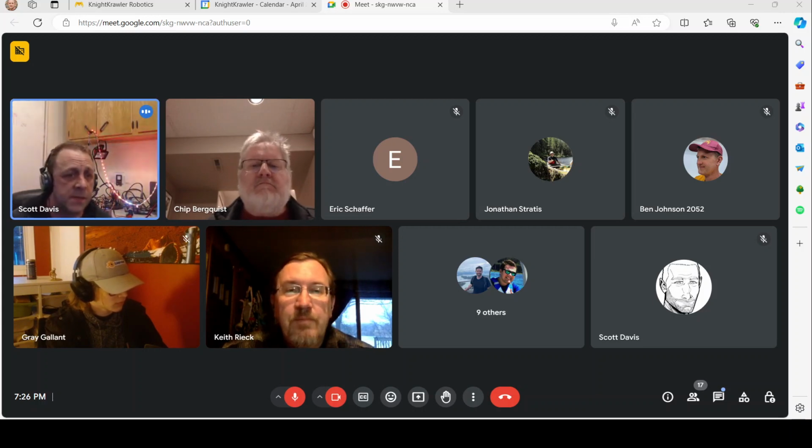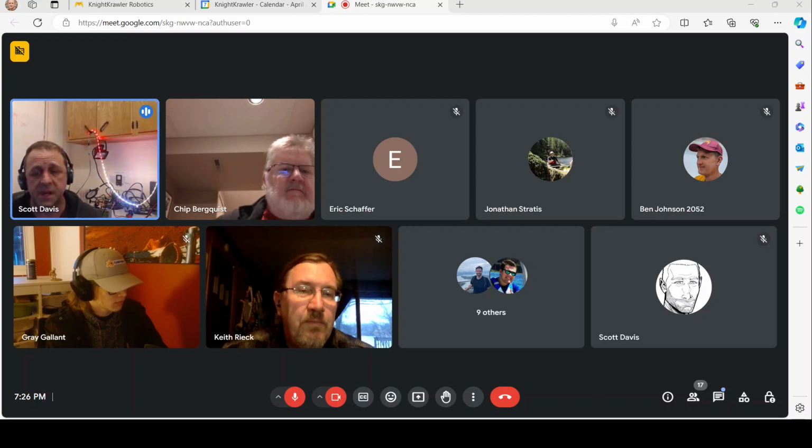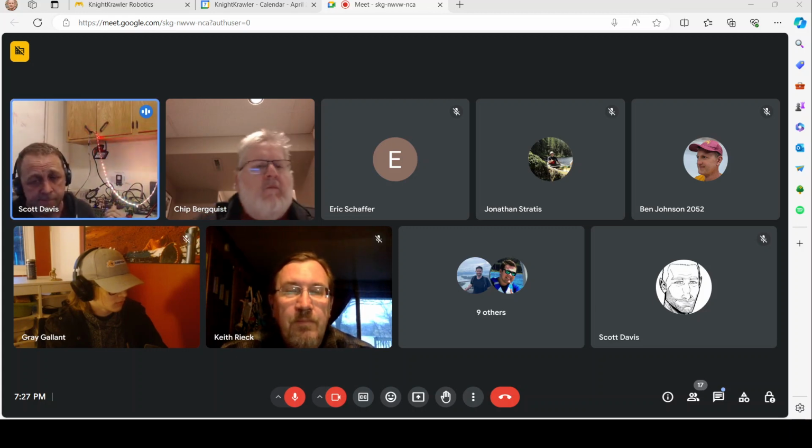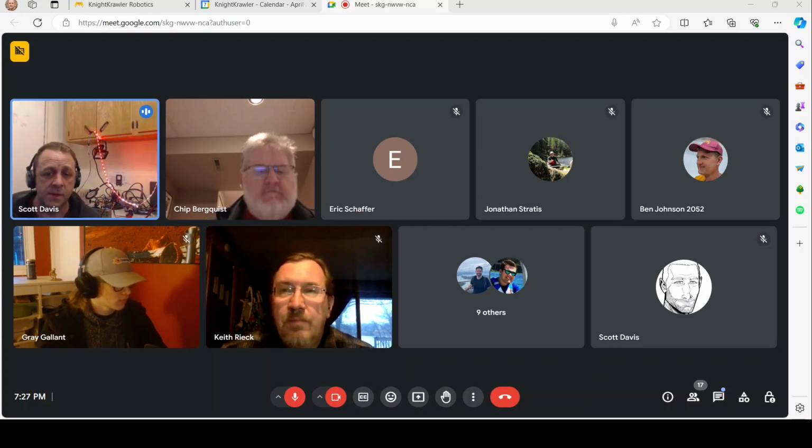Good questions, Chip. So yeah, if you are out of DIO pins and this just is not going to be an option for you, doing something with I2C and setting up a second Arduino so you can communicate back and forth is always an option. Then you can plug it into your RoboRio's I2C ports, and you'll be able to talk using the I2C protocol to your Arduino chip, and you can send and receive that way.